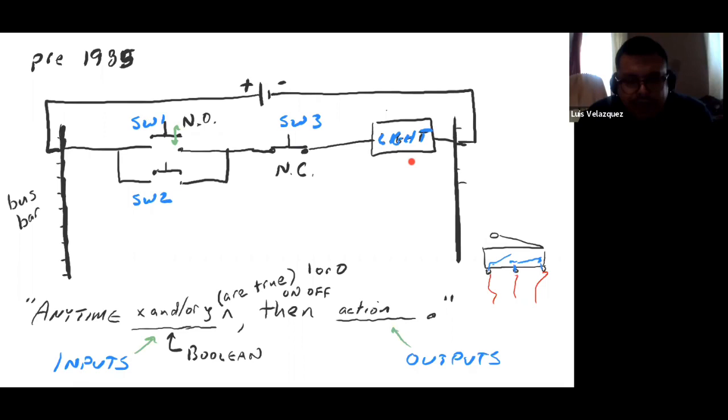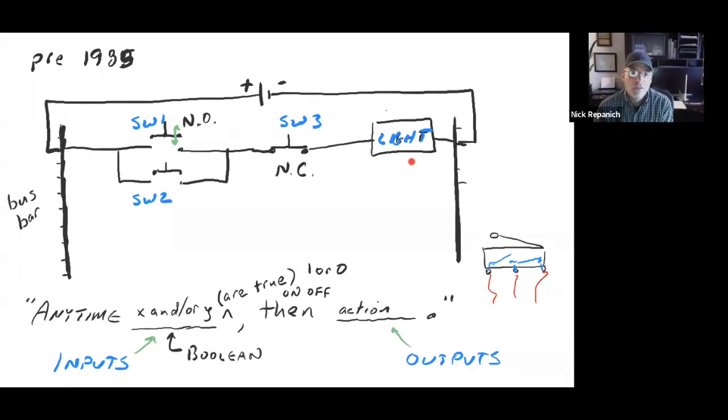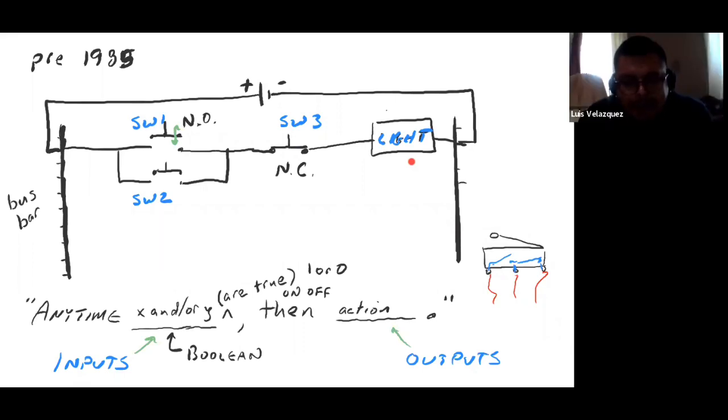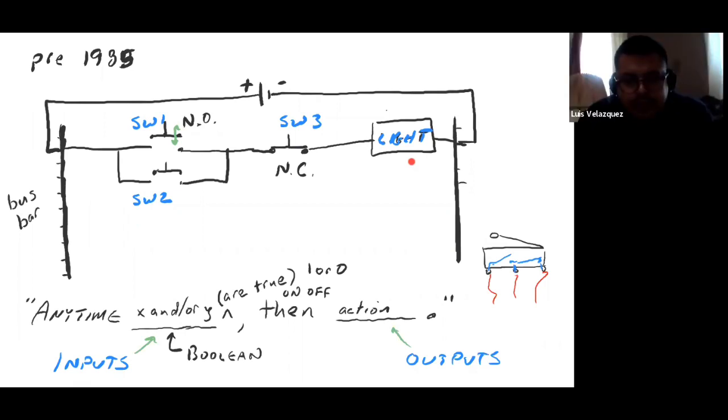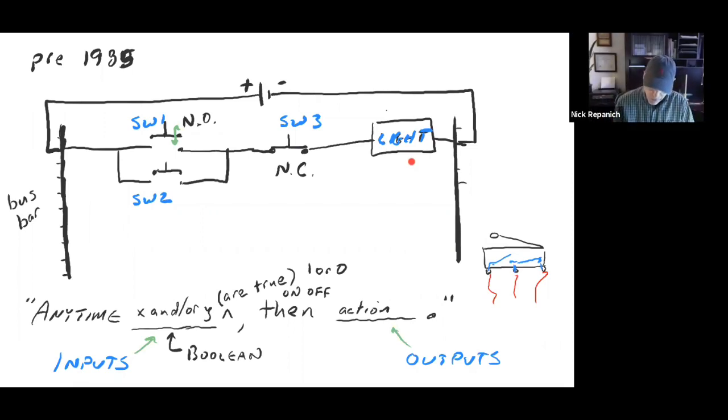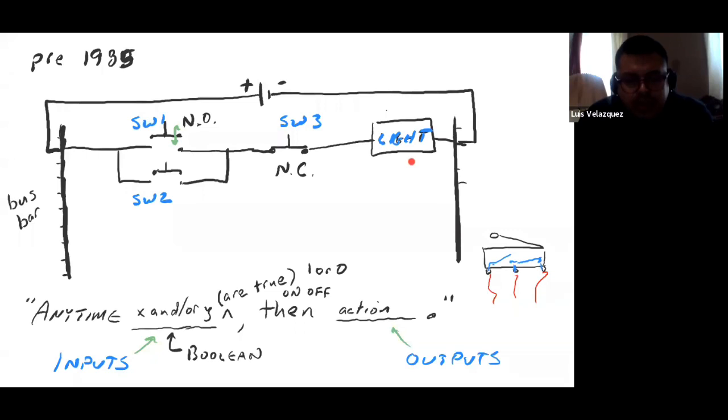Switch 3 always has current going through it until somebody pushes the button and then it's open. So it's just the exact opposite logic, that's all. You can have switches that are normally closed, and when you push the switch, it breaks the circuit instead of making the circuit. It's just the opposite of the logic, whether the spring is holding it closed or open, and you push it, you either open or close it. So you can make it one of two ways. Make sense? Like the push on, push off kind of switch, except this one was always on.